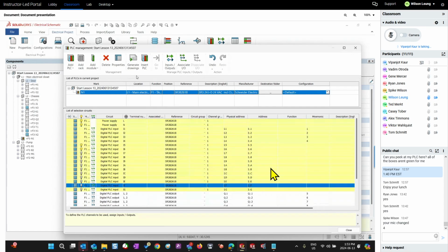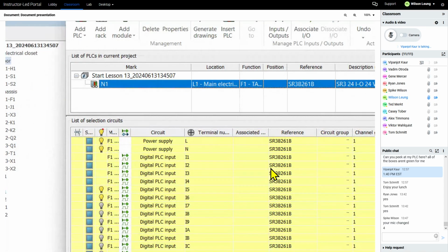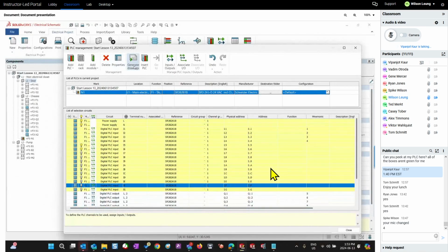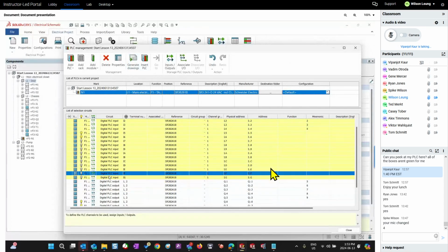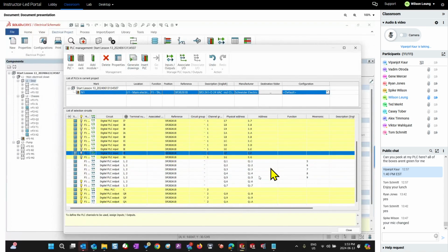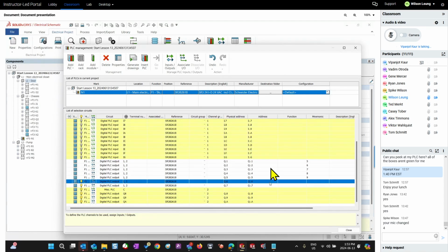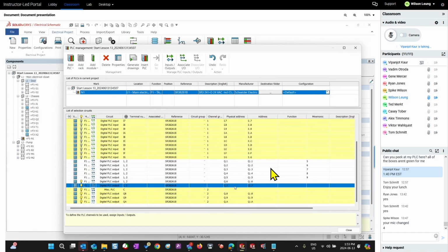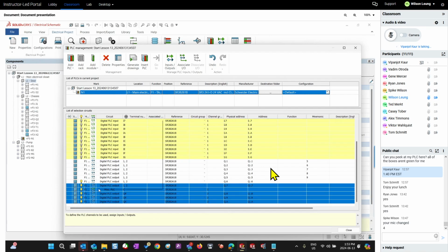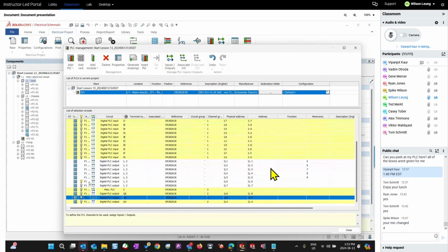So now if I'm going to generate a drawing, I'm going to see anything that has a light on or anything that I'm using. So anything that has light toggled off will not be shown in my drawing when I click generate drawing button. So same way for the outputs. If Tom tells me, VIP, show 1 extra output number 6, I might use it in future. Sure. Then I'm going to grab number 7 and anything after holding shift, right click, I'll say hide them, don't show them in the drawing, and I'm leaving one spare.